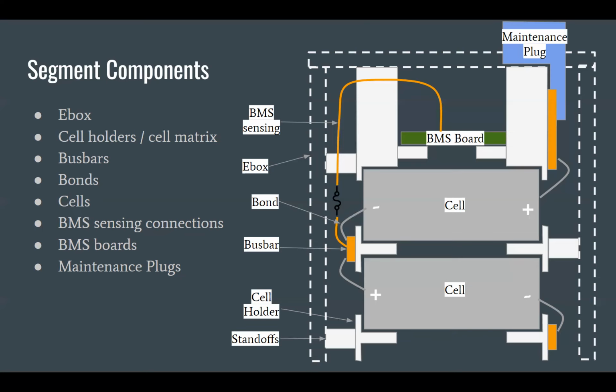Because remember also, by the rules, all of the connections in the battery pack that actually conduct battery current are officially critical fasteners. And for anyone who's familiar with the rules, all critical fasteners in the battery pack have to be positively locked. Positive locking essentially means if you have some form of vibration in the vehicle, that fastener will not be able